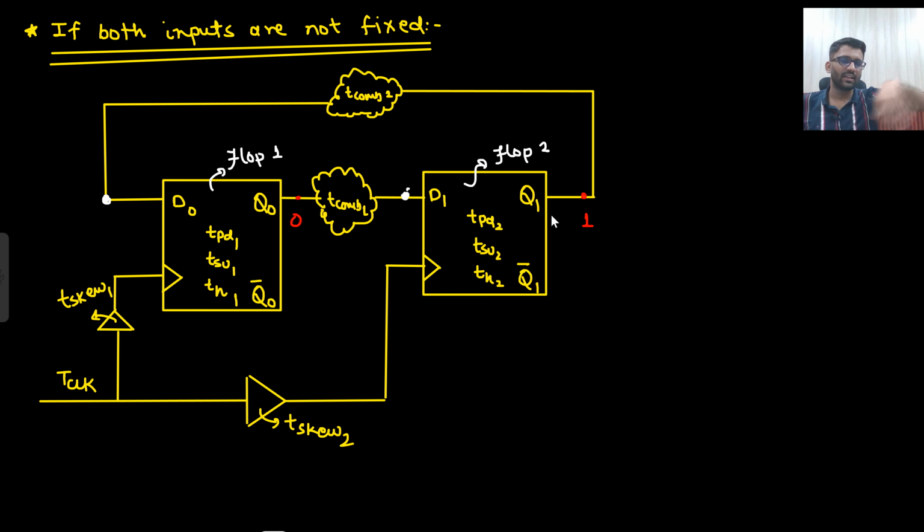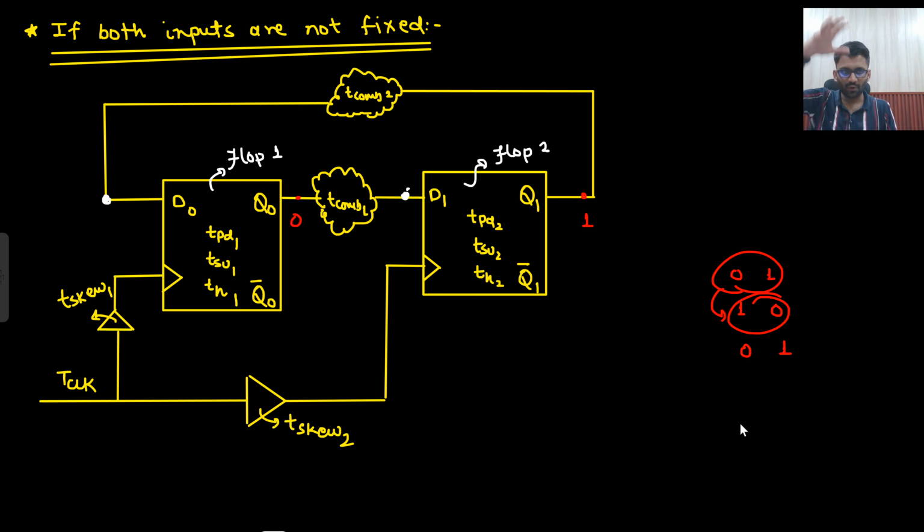Okay, then you will get to know that this will keep on flowing in this particular loop only. Like if this is 0 and this is 1, then this 1 will come here, this 0 will come here, then this 0 will come here, this 1 will come here. So this waveform you will get, this will be a mode 2 counter. This will be a simple ring counter, and you will draw the waveform and you will realize how much hold margin you require, how much setup margin you require.